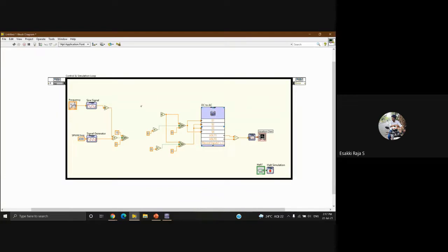So here, I'll just repeat this. We are going to use SPWM signal strategies. For that, we are comparing a sine and a sawtooth signal. Based on its output, we are going to pass a data. Here we have our sine signal, which is going to decide the final frequency of the signal. So this signal only we need to compare with 0.